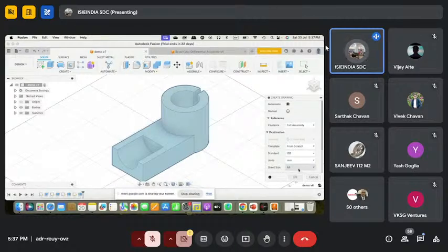And also you have to describe the sheet size. Generally the sheet size is A3, but it is up to you. You can want a custom sheet size or A3, A2, A1, A4, whatever. Also, you have to set the units. I have set the units in mm. You can choose according to your need, in inches or mm both. Then standards. We have ASME standards and ISO standards, and you can choose from here, and then you have to hit OK.